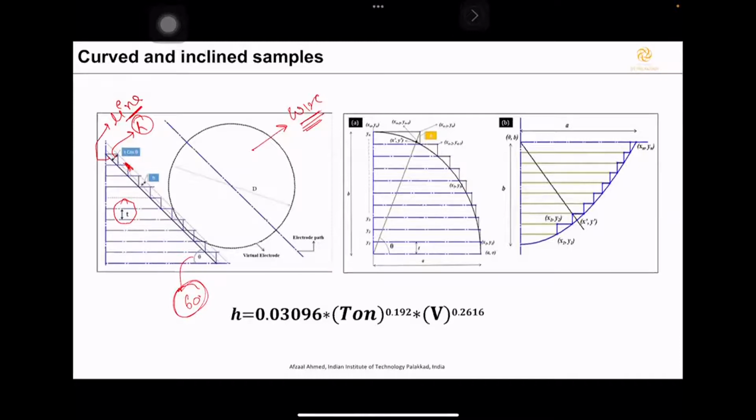So as you can see here, this is a convex surface. A part of it we have not modeled because it is symmetric, so we have taken a small part of it. And if you see here, the step on this surface is gradually reducing. For such a profile, we have to write our own code. This can be done geometrically. We can do simple geometry, use trigonometry, and find the number of passes and those things.